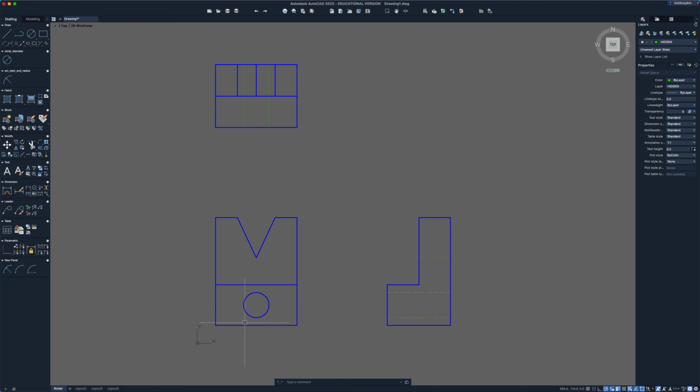If this happened to be a rectangular hole going through here, then I wouldn't do anything in the middle of this. But when I'm looking at the right side view, this is just showing that there's something at the top, something at the bottom. I don't really know what shape it is, but I can obviously look to the left and see it's a circular hole. But we generally put a center mark here. So to do that, center line and center marks.